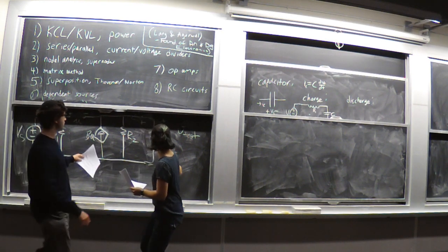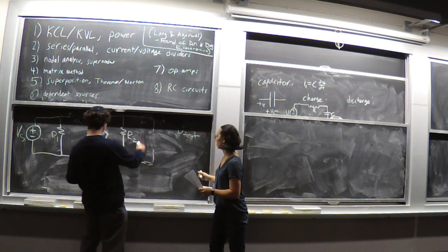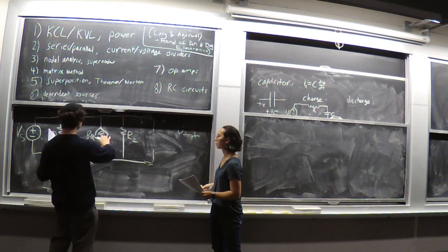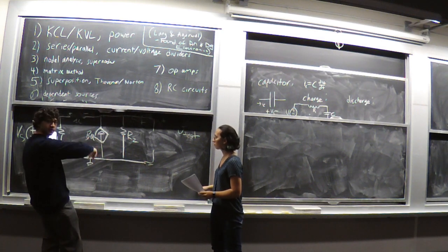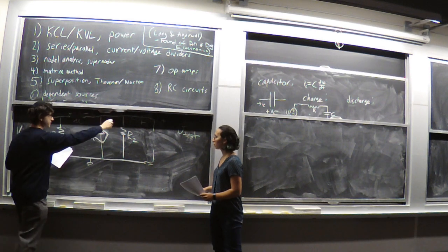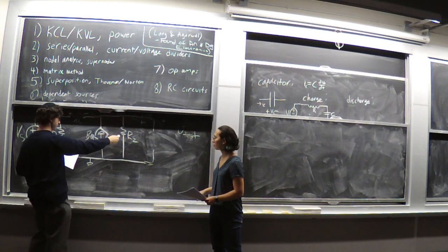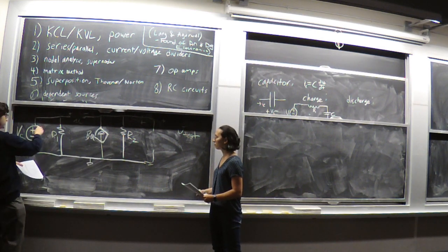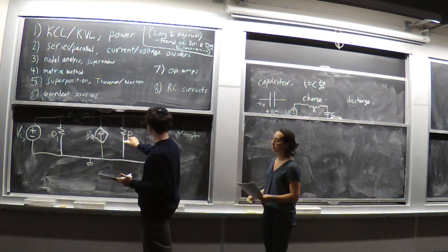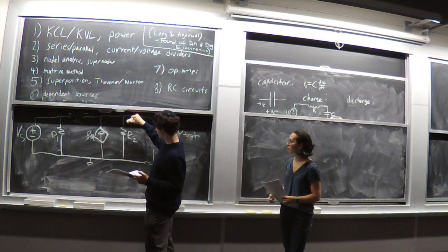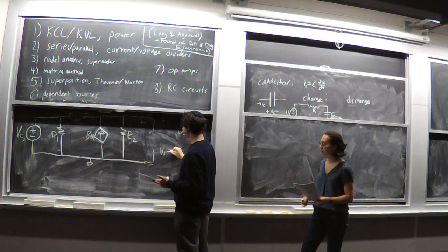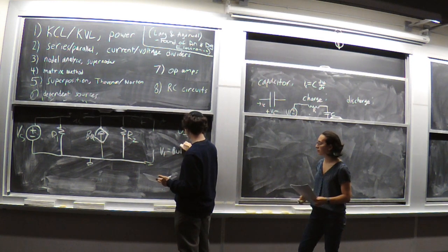Well, to note, what we're trying to solve for is this node up here. We defined ground at the bottom. And so this node up here, what we see is two separate little loops, right? There's no connection here, and so this loop is just going to have this current flowing through this resistor, and this is just a voltage source and a resistor. And so we can solve for V-test in terms of these. We know that this current is just going to go straight down through R2. And so from that, we have that V-test equals B times U times R2.